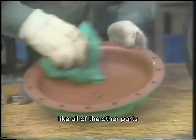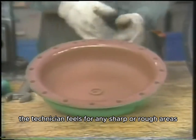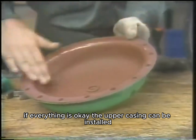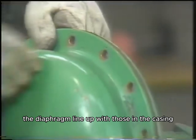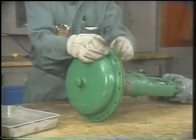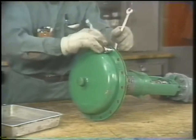Like all of the other parts, the top half of the casing should also be clean before being replaced. Again, after wiping it off, the technician feels for any sharp or rough areas which could damage the diaphragm. If everything's okay, the upper casing can be installed. After a check to make sure the bolt holes in the diaphragm line up with those in the casing, the upper casing is placed in position and its bolts are replaced. Once all of the bolts are in place and the casing has been evenly tightened, reassembly is complete.